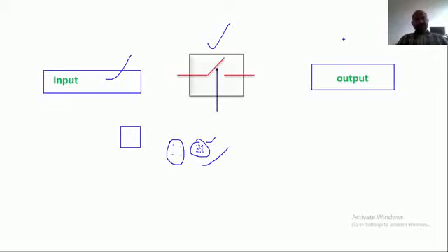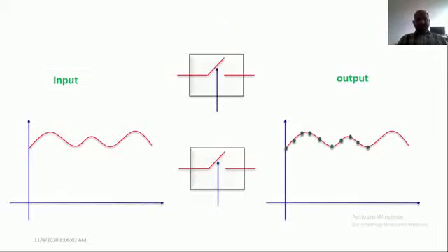So here I would like to show the input signal. This is my input signal, which is an analog signal. This analog signal is converted into the discrete signal or the sampled signal. For your convenience I am taking it as a sampled signal, but in the technical format we call it a discrete signal. The input signal is there in the continuous form. So I'm assuming that this is the time period t, and this is the amplitude.